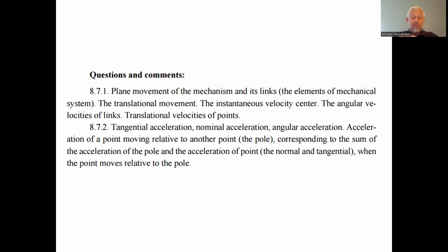Questions and comments. The plane movement of the mechanism and its links, the elements of the mechanical system, the translational movement, the instantaneous velocity center, the angular velocities of links, the translational velocities of points: I just remind you that we have to know these concepts. Plane movement is a movement where all points of the mechanism move parallel to a definite fixed plane. Translational movement is without rotation.